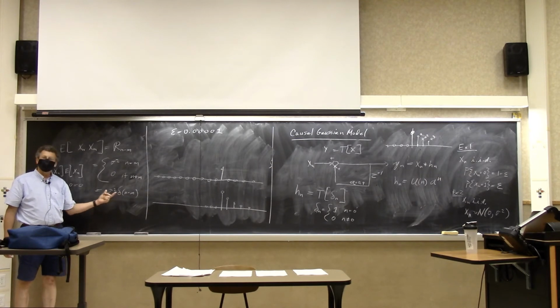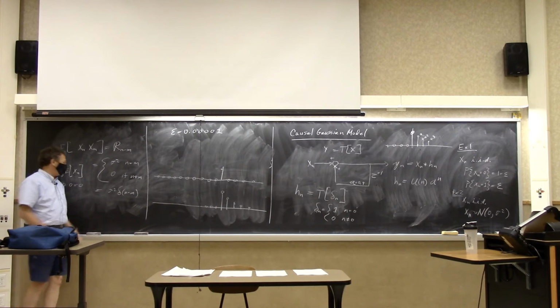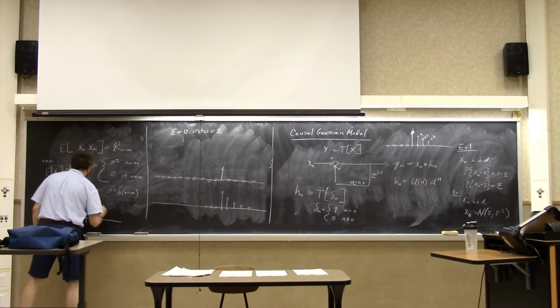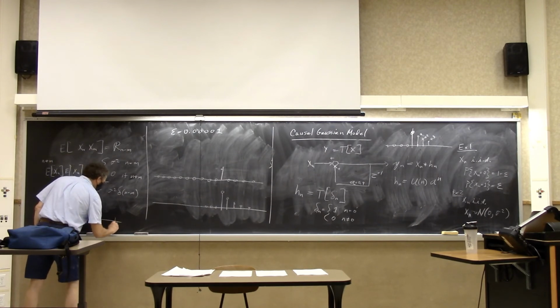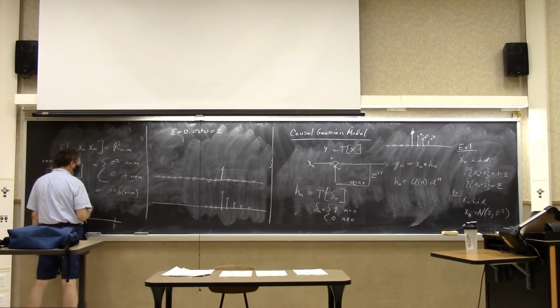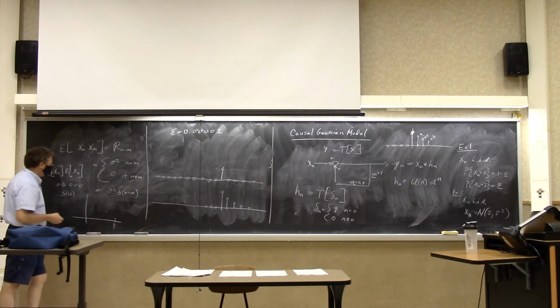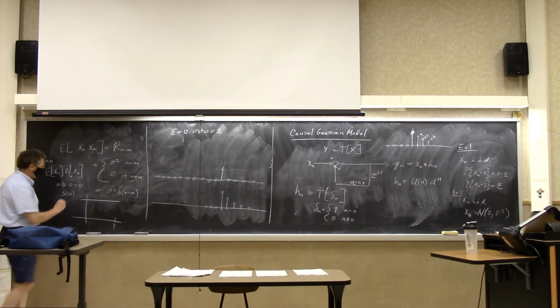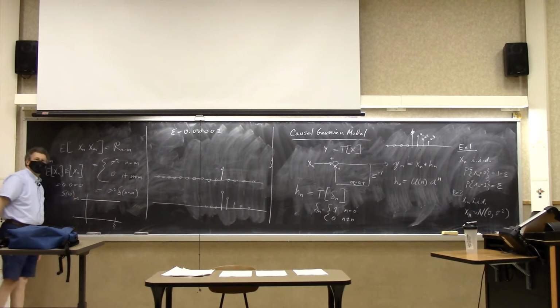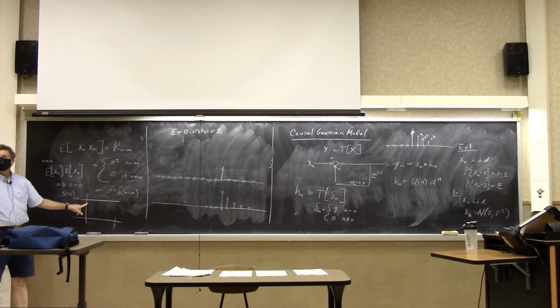It's a Fourier transform of the autocorrelation. So what's the Fourier transform of this autocorrelation? It's sigma squared. So it's flat. So the power spectrum, S of omega, between 0 and pi, it's always going to be symmetric because it's a real valued function. It's just constant with value sigma squared. That's called white noise, okay?